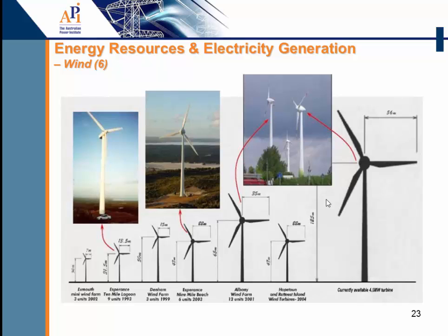For example, in a wind generator, we can extract the maximum power point via the mechanical part, which is the wind blade. We can turn the pitch angle in order to track the maximum power, as well as using the generator. We can track that using different electrical operating points in order to get the maximum energy out of the available wind.